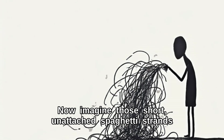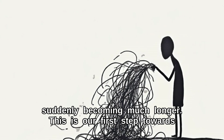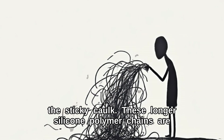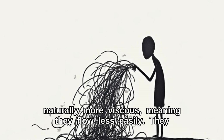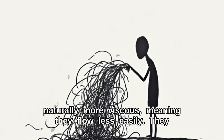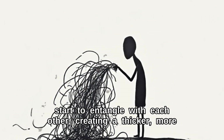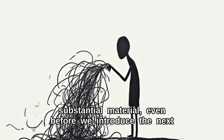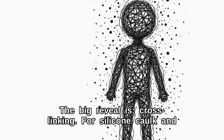Now imagine those short, unattached spaghetti strands suddenly becoming much longer. This is our first step towards the sticky caulk. These longer silicone polymer chains are naturally more viscous, meaning they flow less easily. They start to entangle with each other, creating a thicker, more substantial material, even before we introduce the next crucial step. The big reveal is cross-linking.